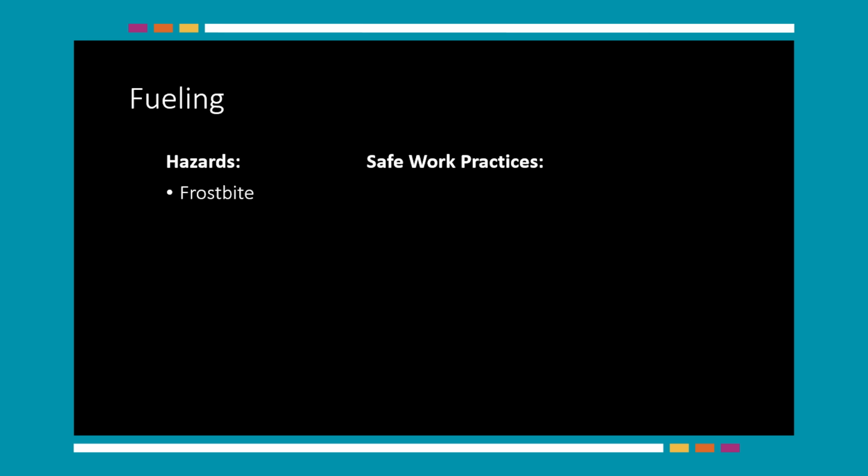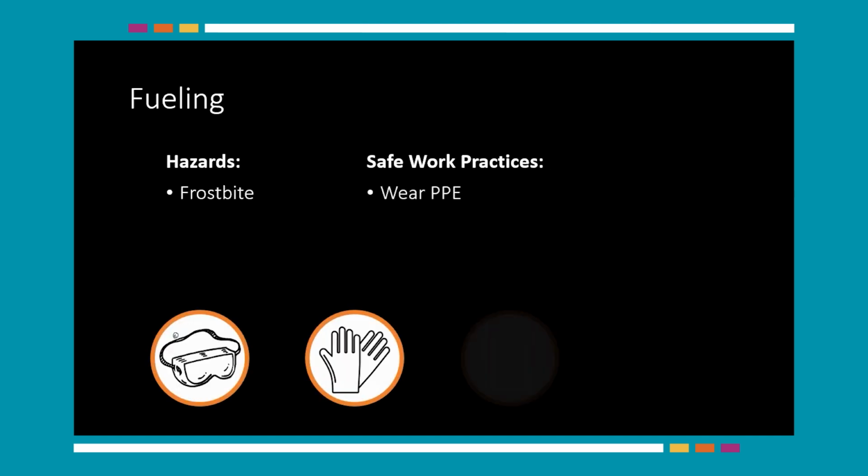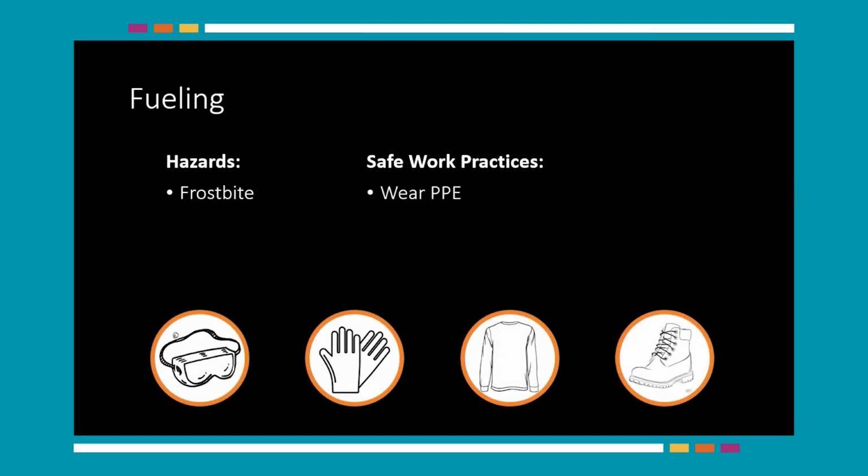Frostbite is likely to happen when disconnecting and reconnecting a propane tank to the forklift's fuel line. PPE, including safety glasses or goggles, neoprene or rubber gloves, a long-sleeved shirt, and safety shoes should be worn.